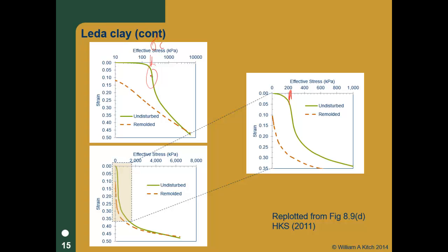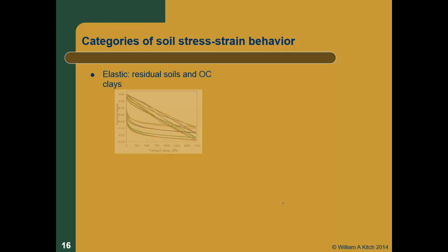So what can we conclude with this? We're going to categorize. Here are my conclusions. Soils can be modeled pretty well as linear elastic. I'm talking only about monotonic loading here. Obviously, when you unload, it's not elastic, but at least on the loading curve, that's pretty linear elastic. And if all I want to do is calculate settlement, I don't care about the unloading, right?